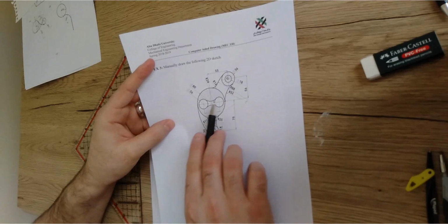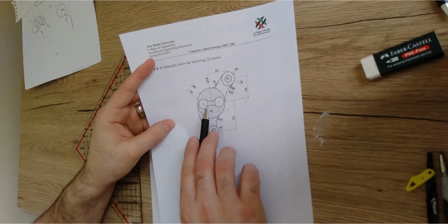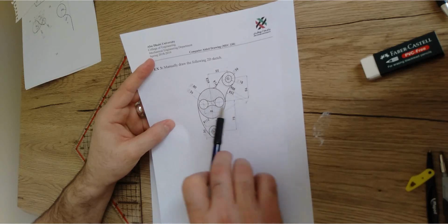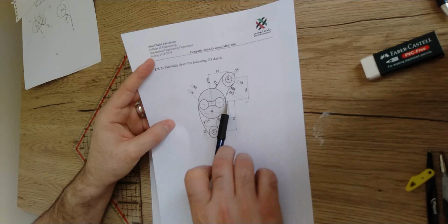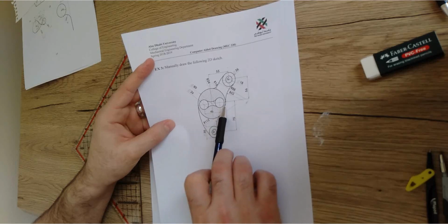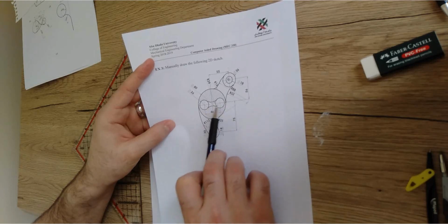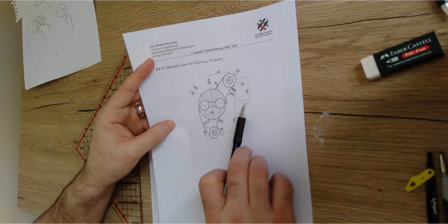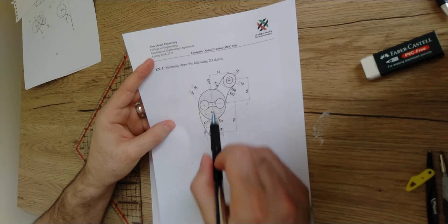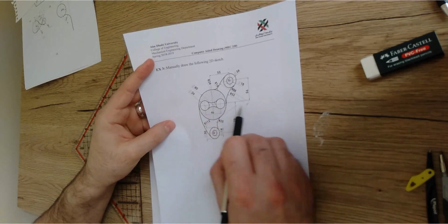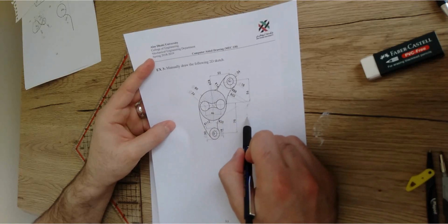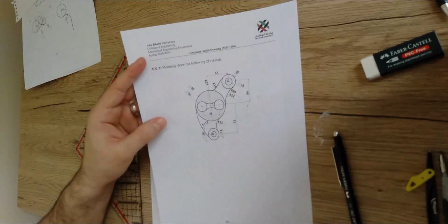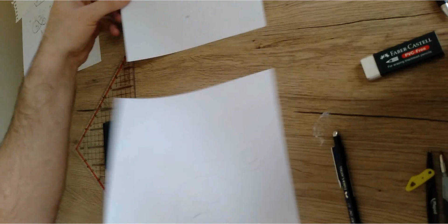How about this center? Because it is tangent to the big circle, I have to use the center of the big circle. So if I ask you to move from the center of this curve to the center of the big circle, are we gonna go over the tangent point? Yes, we do. So what does it mean? We have to add the two already. The radius of the big circle is 40, plus the radius of the curve itself, 52. So the sum will be 92. So from this center I'm gonna fix and open the compass with 92, and for this one I'm gonna open the compass with 70 to end up with two loci to locate the center point of this curve, and this is what I'm gonna do.